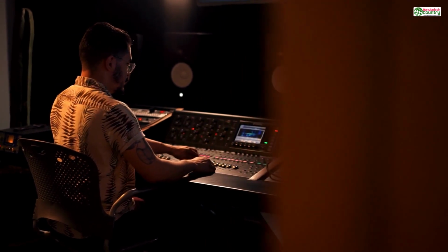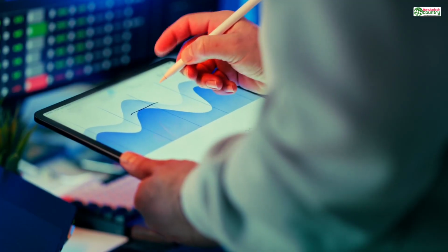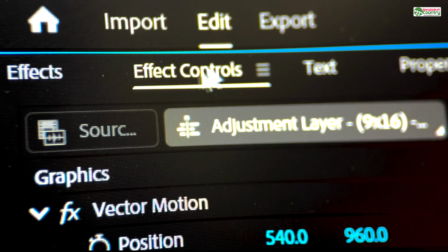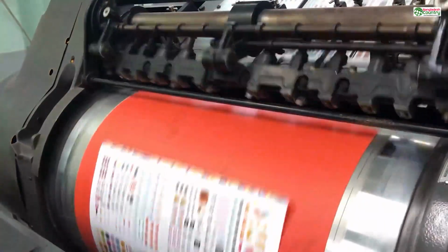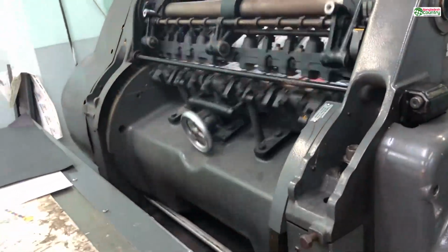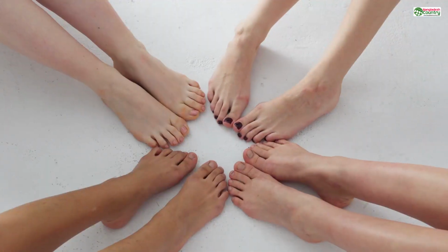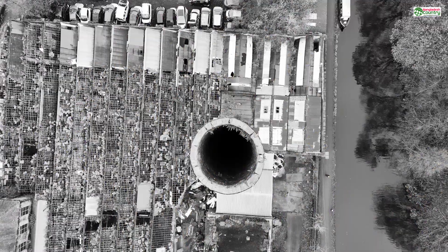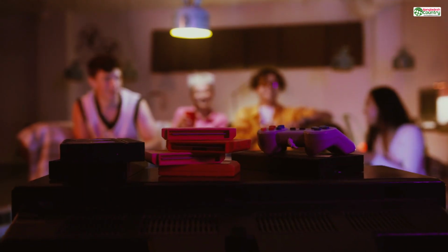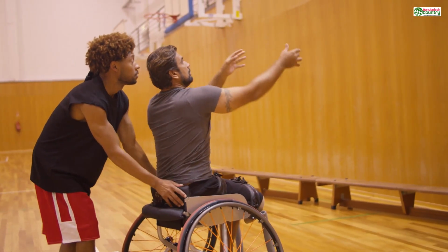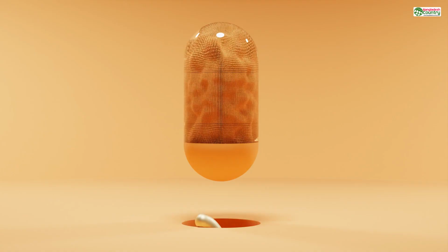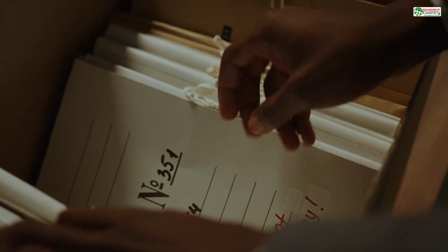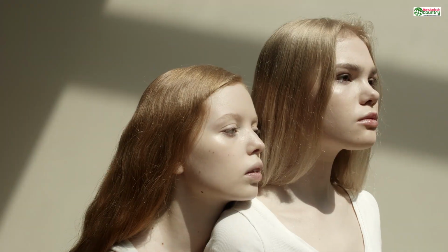It's a digital lost in translation moment. Your 3D software is speaking one language of size, and the printing service's uploader is listening in another. The result? Chaos. A beautiful 6-foot-tall suit of armor you designed becomes a miniature for a dollhouse. A delicate 2-inch pendant becomes a massive, unprintable monstrosity, the size of a manhole cover. This isn't a bug. It's a fundamental misunderstanding of how digital objects relate to the physical world. Here's the secret that no one tells you when you start. 3D models in their purest form have no size.